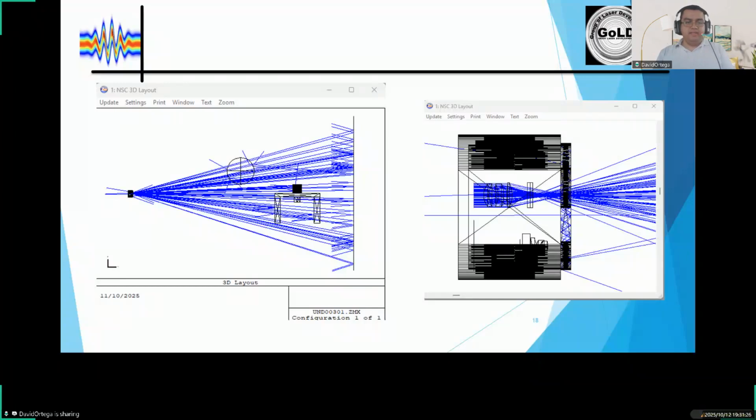But we can conclude that the ZEMAX software can allow you to simulate every object. For example, the table is like a CAD file, but the CAD file doesn't have optical properties. So I need to specify that the table, which has about 40 surfaces, is reflective with a Lambertian profile. The sphere, because it's only one solid, you only put reflective and the Lambertian profile, and the same for the wall. In this case, you can see how the light interacts with every object depending on its properties. Is it a mirror or a lens? They're going to focus the light or reflect the light.